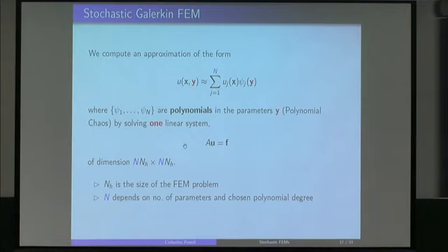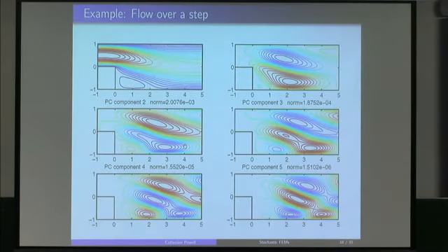But what comes out of these simulations? We don't just compute samples of the solution. No sampling is going on here. What we're doing is producing a functional approximation of the solution to the PDE. So what we get when we've solved this problem is this information, the terms that go in this expansion of the solution to our problem. So we don't get samples of the solution as the output, we get pictures like this.